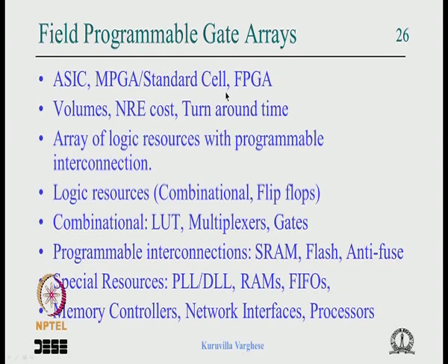So at the beginning of the course we discussed the evolution of these devices. Okay, we have discussed the evolution of the PLDs in greater detail, but since we discussed this at the beginning of the course, I will just briefly mention that ASIC is something which is built from scratch. Okay, the designers might use some kind of standard libraries to implement this, the ASIC libraries, but more or less it takes a huge amount of time and huge cost, which is called non-recurring engineering cost. That means there's a one-time design cost, a lot of EDA tools are required, a lot of designers' time is required, and one needs to set up a foundry line to fabricate this.